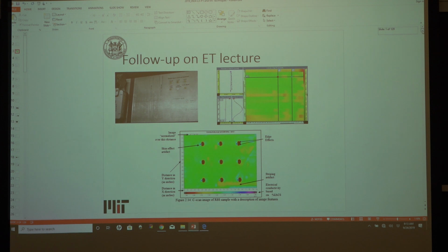Because if you're going over just with the hand, you will get these in imaging, and it's only from experience that you would know that this isn't really a heat affected zone. If this was a sample where there could be residual stresses or issues from the metallurgical processing, you can get a false positive by not knowing the difference between a heat affected zone and a sample that wasn't held down properly at some point.